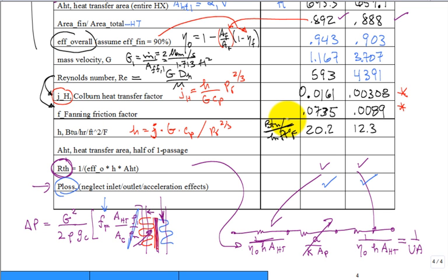Maybe we could go through that, because I got really, really low numbers. Did you account for the hour and the second difference? Because what are the units on G? Yeah, so 3,600 is needed. That's right. Because second and hour, yeah. Probably would have been better just to convert G into mass per hour and use that as your primary unit of time.